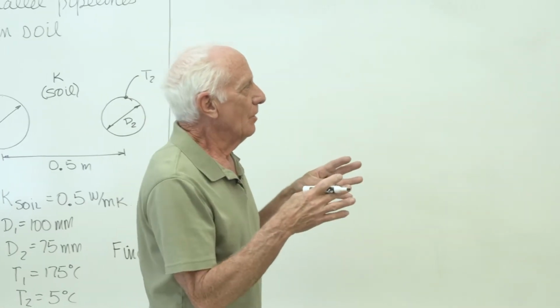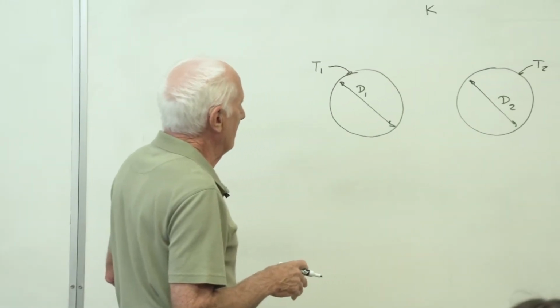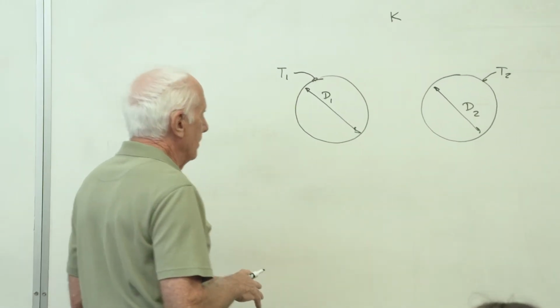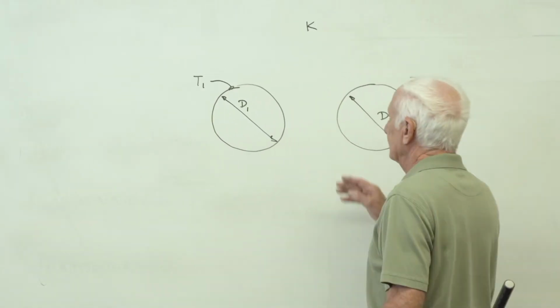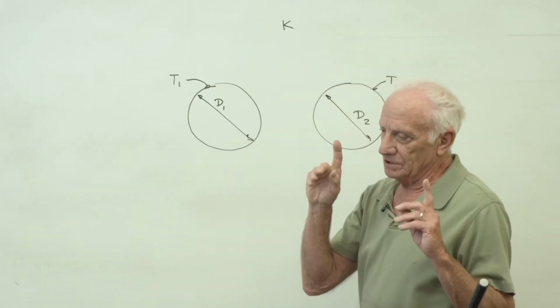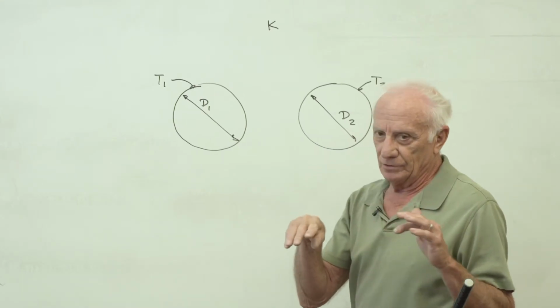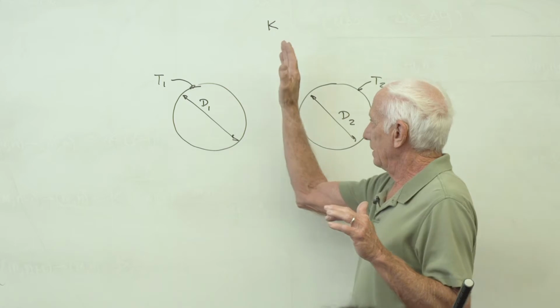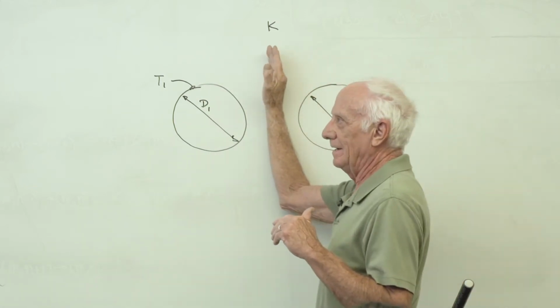Okay, back to this. We're going to draw a flux plot. First of all, is there symmetry? Don't forget rule 1, flux plot: look for lines of both geometric and thermal symmetry. Try that guy. No. That guy. No. This guy.